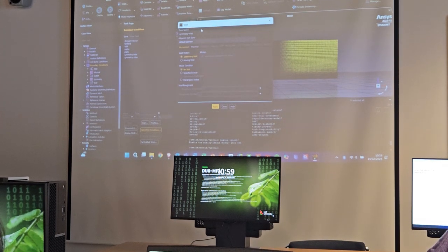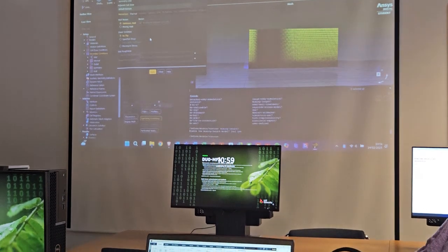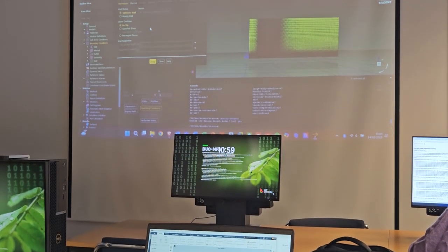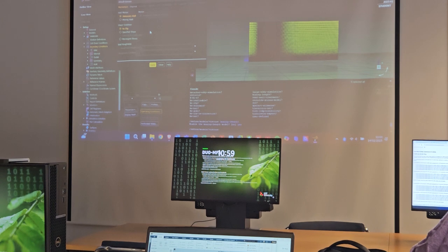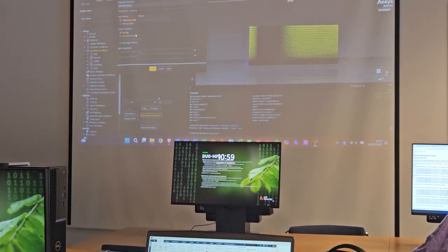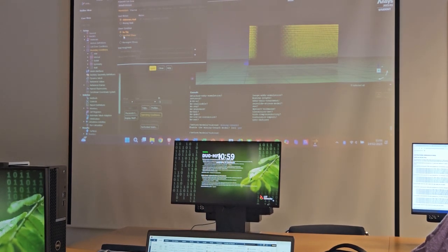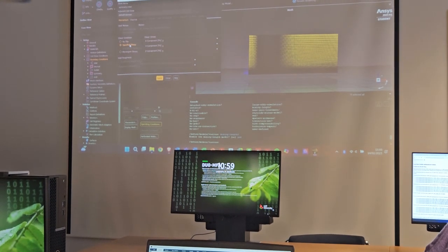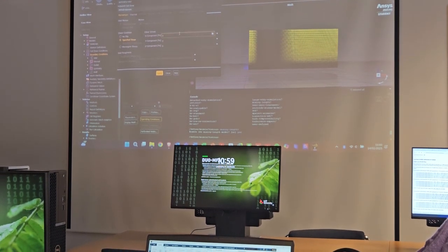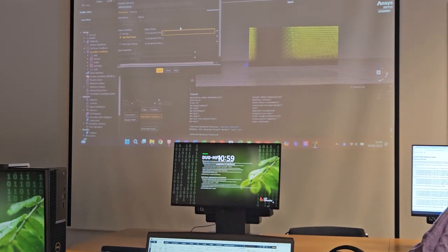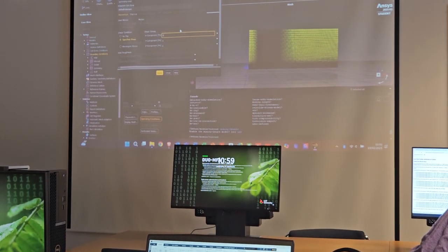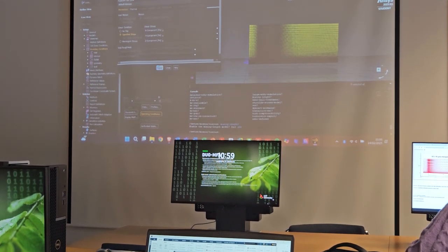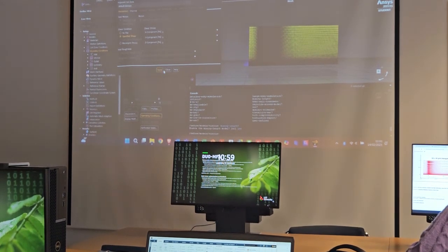So we select wall type, but of course we don't want shear forces on the flow in that region. So we need to set it like a slip wall. That means that we can change the shear condition to specified shear, and then we set the shear stress equal to 0 for the 3 components. That means that this wall is not accepting any shear stress on the floor. And it applied.